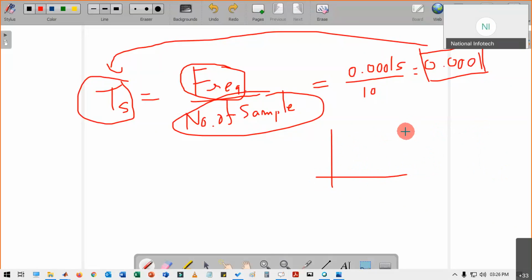No, your number of samples will be fixed once you have selected it in this block. You have increased the point, it was 10 here, and accordingly you will have to enter one more zero here. Then you will get this 10 kilohertz pulse.